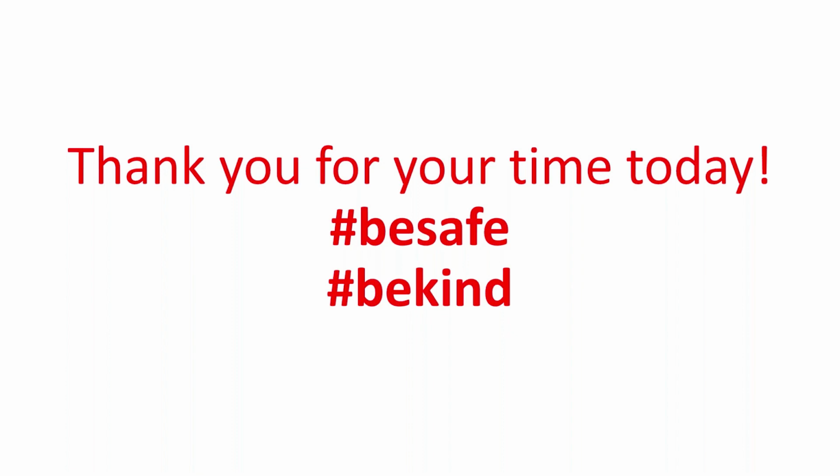So if you had, for example, a circular base cylinder in 3D and it had objects coming off of it, you can trim and split those objects off of the cylinder. So you might have some nuts and bolts that have been modeled onto the cylinder, but they're part of that solid and you want to take them off. So Trim Split trims the nuts and bolts off the cylinder and then splits them away from the solid. It's such a simple little app, but it just works, and it's one of my favorites.